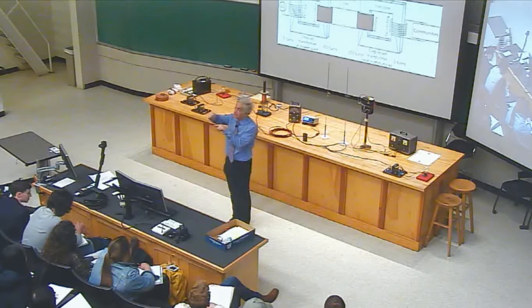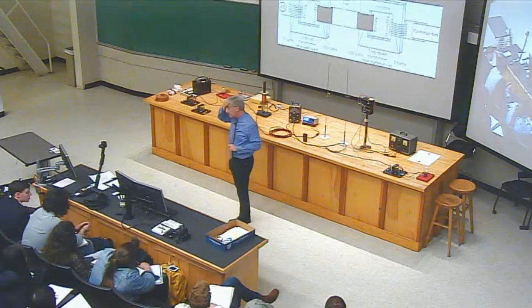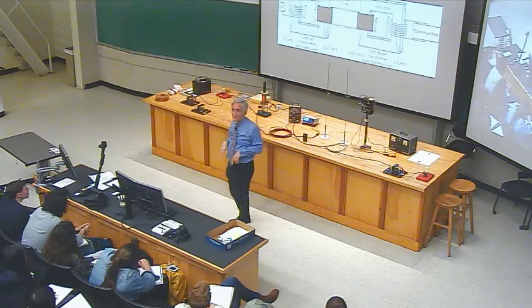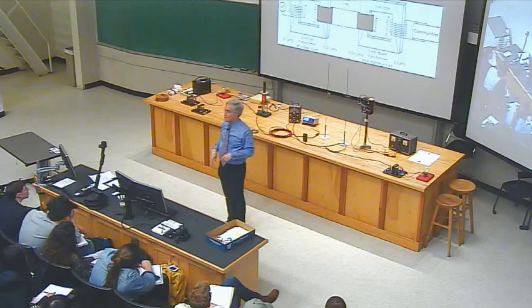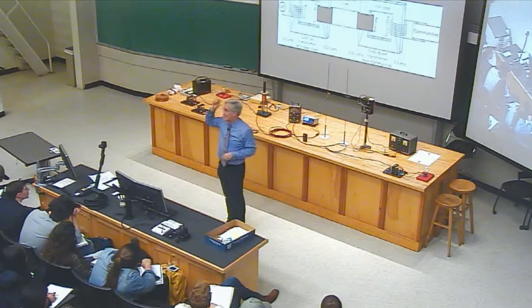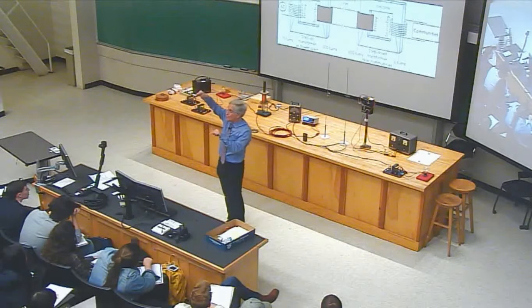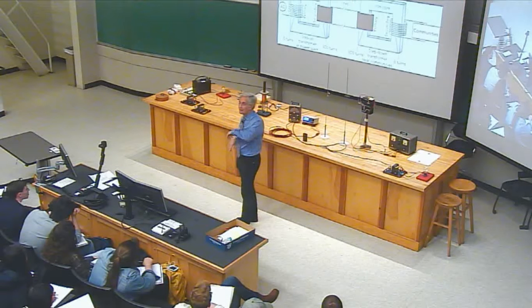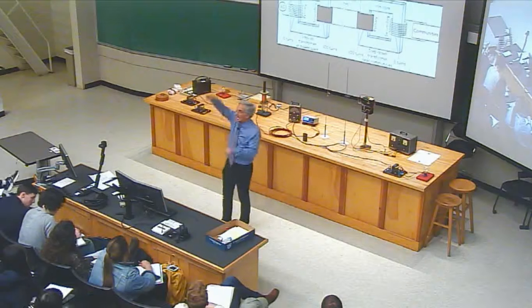The reasons don't matter. But so actually the voltage gets higher than it's stated, which is a little bit of a safety issue, but also in those long distance power circuits, if you've got a 1,000,000 volt power line, that actually means that it peaks at 1.4 million volts when it hits peak voltage. And the peaks matter because that's when sparks occur. So they're limited in voltage by the peaks.